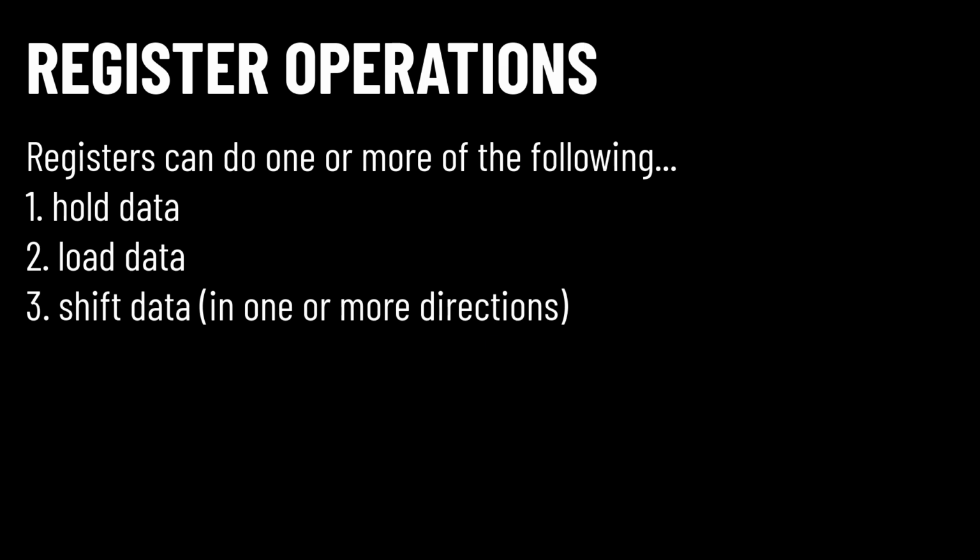There are multiple operations that a register can do. Hold, the outputs do not change when the clock ticks. Load, one or more outputs are updated when the clock ticks. And shift, each bit is cascaded through the flip-flops in one direction or another.